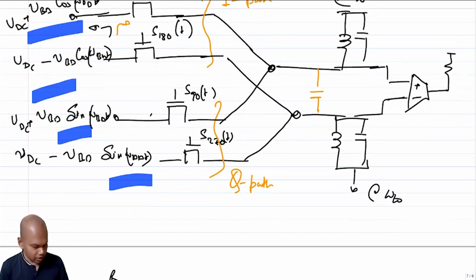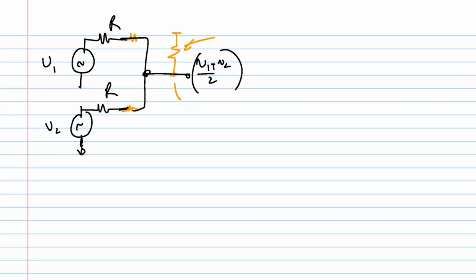Okay, while this type of mixer works and it's perfectly fine, the problem with this is you do not get enough gain, right? In fact, you do not get any gain. So all the gain is now being asked of the final stage, which is a power amplifier, which we'll get to in the next class. But the key problem with a passive mixer is that it does not have any gain. Now, how do you get a gain?